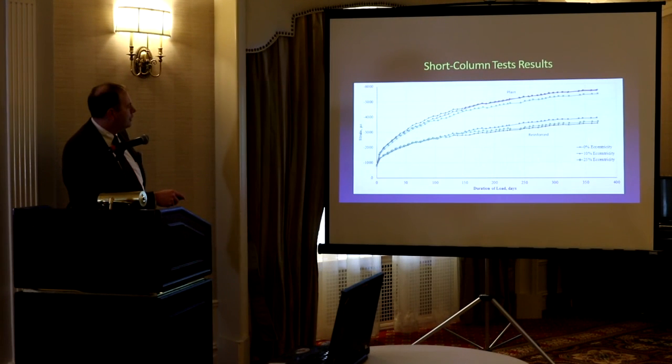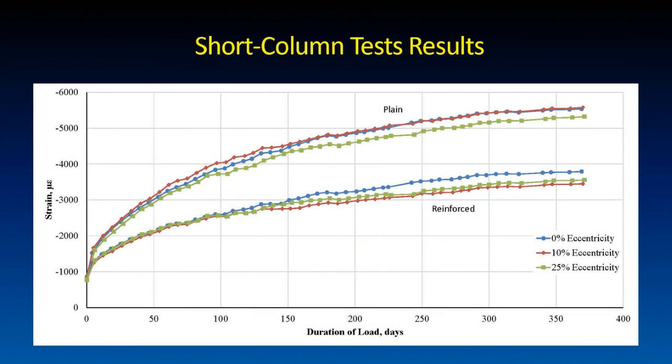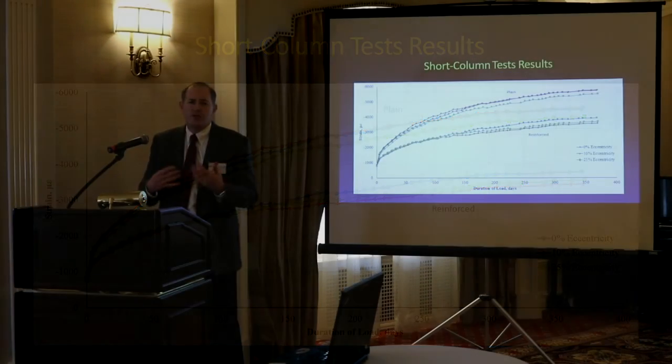But if I take a look at a duration, let's say reinforced here, I'm at about 250 microstrain, so I'm coming up now. So there is some more strain that will develop. Obviously the bulk of it's all happening here, but there is some more. So we were cognizant that we only loaded to 100. So I feel still better with a 1.0 than that 0.6 that I was mentioning here for the sustained load effect.